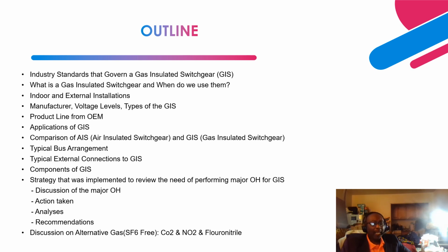For an oil to SF6, basically these typical connections are to the high side of a power transformer, so that basically inside the transformer we have oil as the insulating medium, and on the side of the SF6 gas bus enclosures is SF6 as the insulation medium. So that is why we have oil to SF6 as an interchange point of connections between the power transformer and the GIS switchgear.